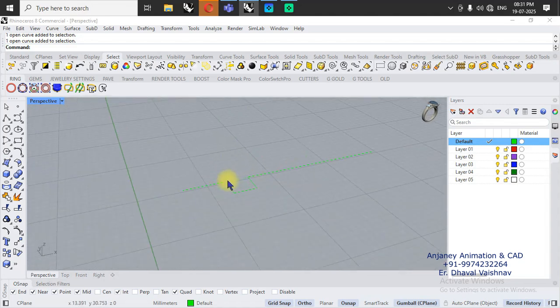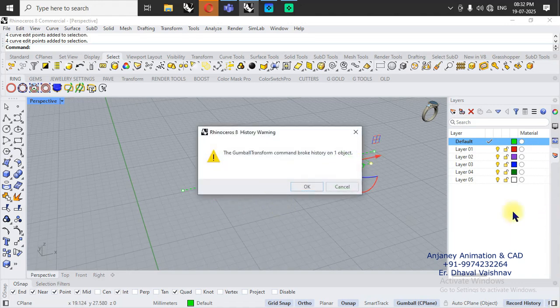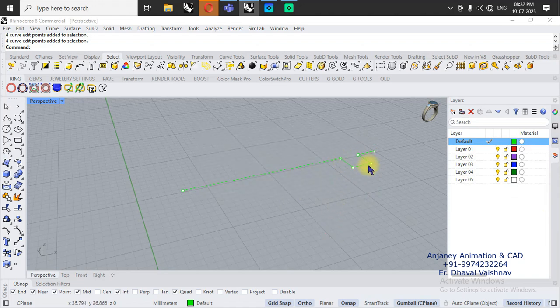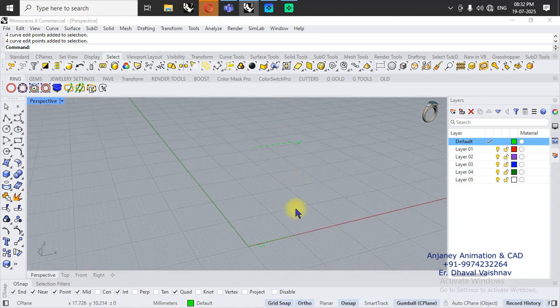Okay, now I want to change this rectangle from this point to this point. So select the line, turn on this edit points and select these points. Now click on this option. See, I have selected all these points. Now click here and type in 6 mm distance. So all the points will be moved at this distance. Okay, now we need to use only subdivision options.